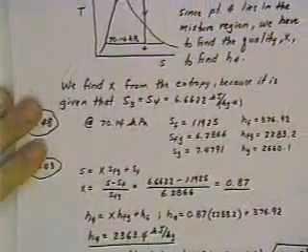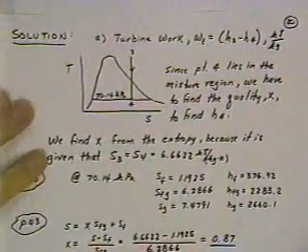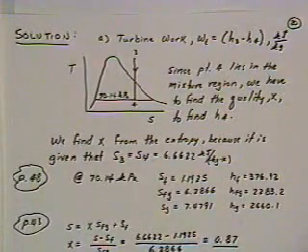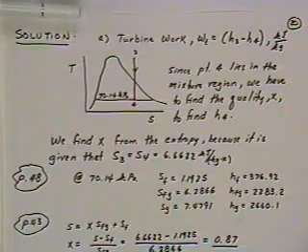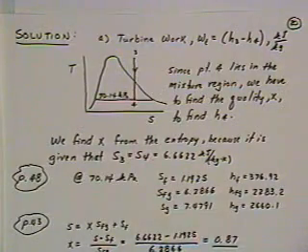Okay, so let's go through this on solutions, and we're going to assume that this is sort of one problem at a time, and we're going to go through and analyze each one of them in order to come up with the work. So turbine work, the work of the turbine. This is again a device that we talked about. It's a device that has a control volume approach, typically one inlet and one exit on these simple problems for simple power plants, and we ignore kinetic energy, we ignore potential energy, we ignore any heat losses, and everything's well insulated.